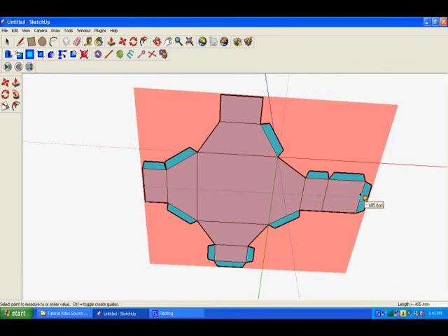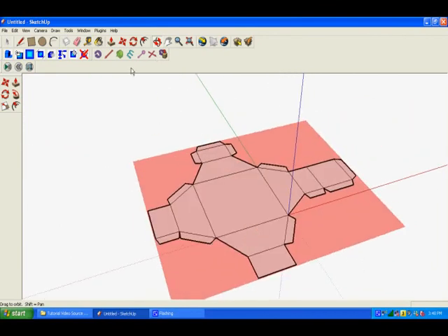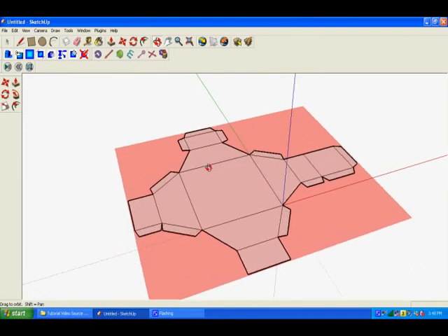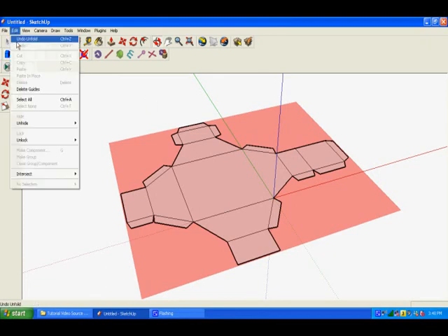And that just lets you know if the object you design is too large and if you need to scale it down. And there's lots of scaling features in SketchUp to make that easy enough to do for objects that you do happen to create too large. So let's click on the undo unfold so we bring it back. And now we're going to move into grouping and sizing.